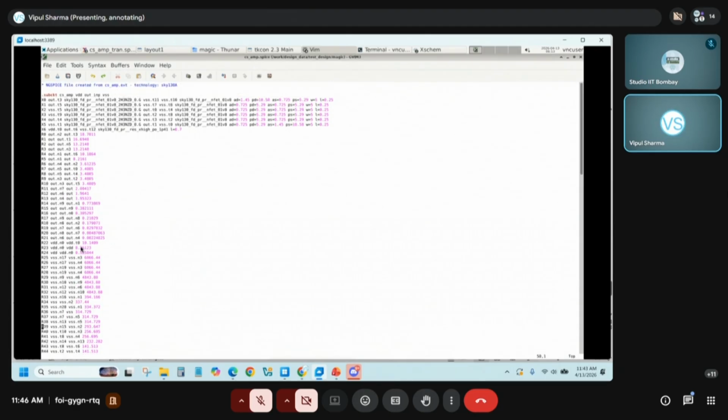validation of our circuit. So now obviously once these things are added, there will be some deviation in our results, and this is what we want to see, like after doing layout, whether there has been some degradation in performance due to these parasitics added. If the degradation is significant, and if it is very much affecting my results, then I have to modify my layout to take care, like maybe if I have used a very long metal wire or some nets are very near to each other. So those kind of inferences have to be made and then rectified in the layout.